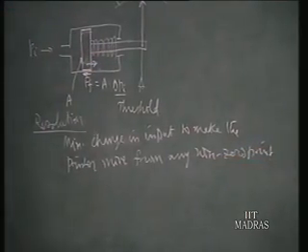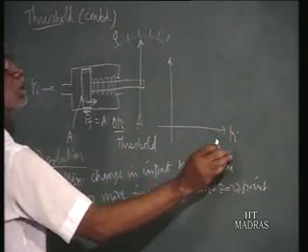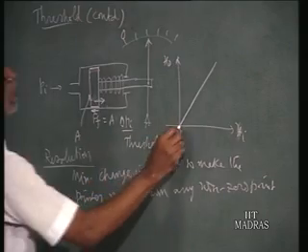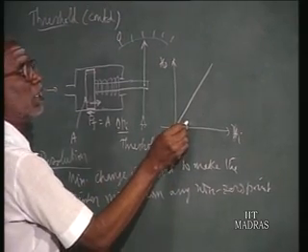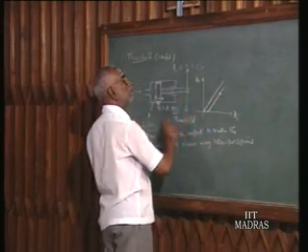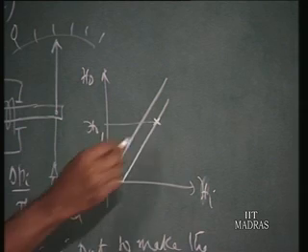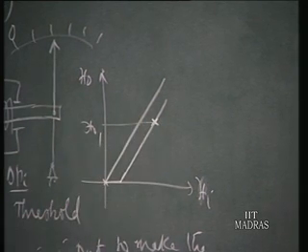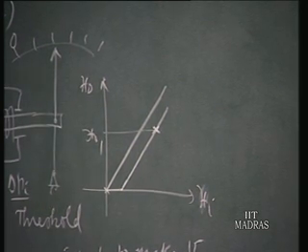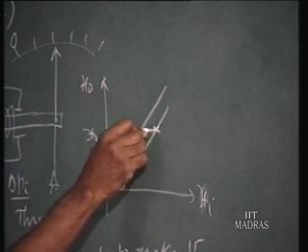That is the definition. Suppose the instrument is functioning somewhere, say Xi and Xo. Suppose this is the ideal relation, and due to threshold the increment is there only after some delta Xi. Somewhere here, suppose this is the operating point, at a certain time this is your Xo1. To make the pointer move from any non-zero point, 0 is here, this is a non-zero point, we have to increase the input by another delta Xi, and if it has to fall, it has to reduce, then you will find it comes here.